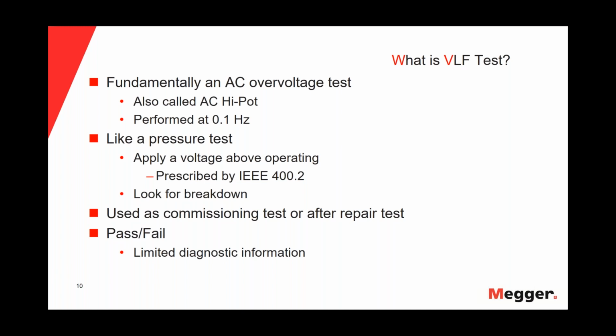In the VLF test, some standards allow decreasing the frequency. Some other standards don't allow that, okay? But well, normally we will say that the official frequency for the VLF test is 0.1 hertz. And the VLF test is pretty much like a pressure test. We will apply a voltage above operating. The voltage will be prescribed by a standard, for instance, the IEEE 400.2, and we will look for a breakdown.